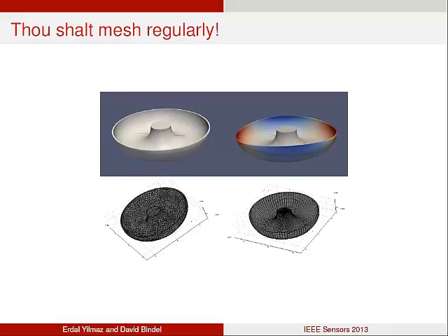Unfortunately, when you do a vibration analysis on this mesh, you see that the frequencies are not equal for those twin modes. For this perfect geometry, your finite element tool ends up having a couple of hertz difference in these vibration modes.